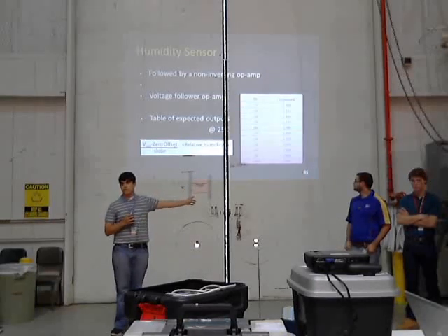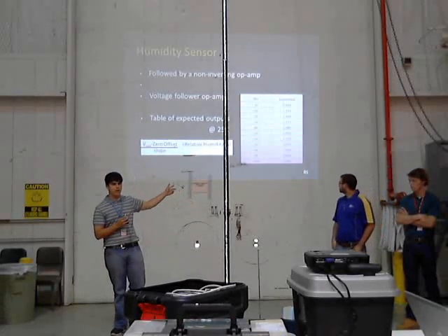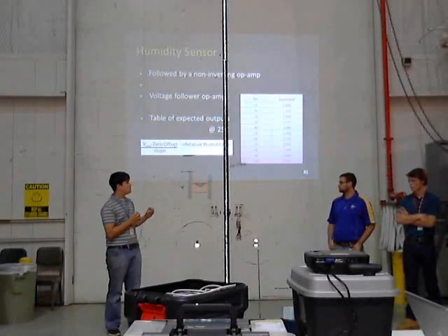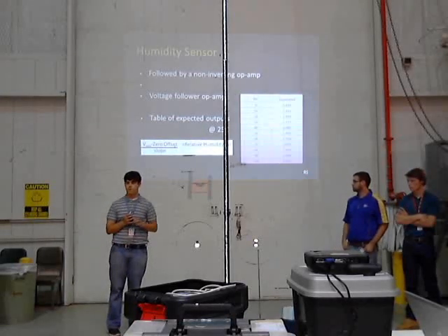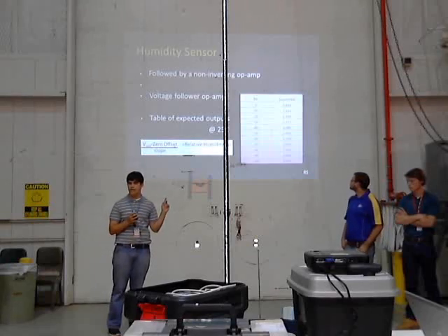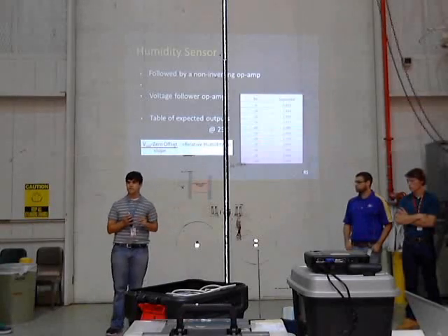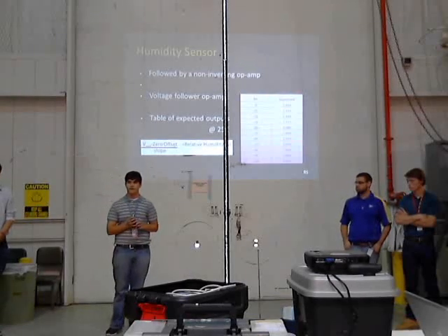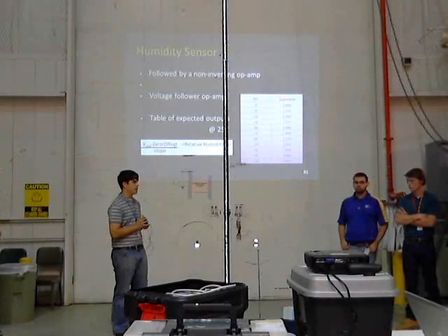These expected values come from our data sheet. Our calculations were about 0.02 off from this, and we can change that using the resistors on board the sensor interface module to change the gain going into the ADC.